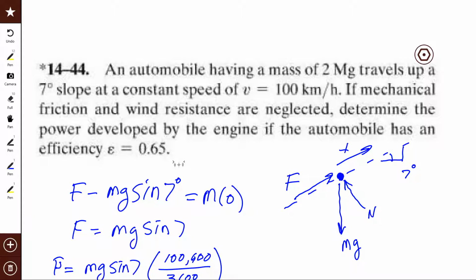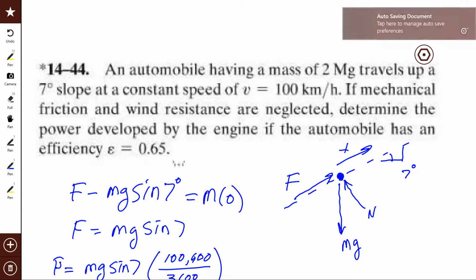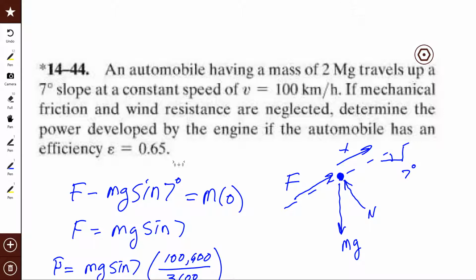You're going to be successful, I know it, and you're going to get to senior design. And about half of you are going to want to get a motor and put it on something to make it do something. And you're going to come to me and say, how do I size this motor? And I'll say, didn't I teach you about power? That's how you'll do it. You figure out what power you need to drive your car up a hill. Throw in a safety factor because you've got friction. And then you're going to say, I need 2 horsepower. That's the motor you need.